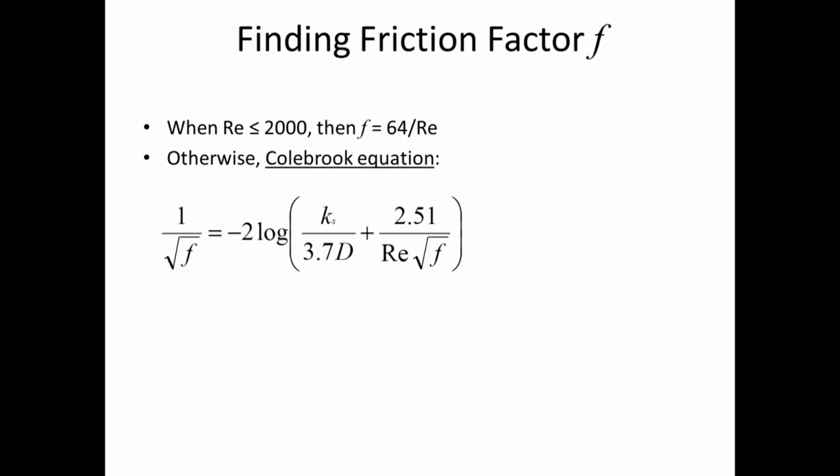Here it is. This is the Colebrook equation. You know, I've been hinting starting in fluid mechanics that there's this really hard way to find the F value. You know, I'd give you the F value in an example and say, really, in a real problem, you're not just given the F value outright. Well, here it is. This is what I was hinting at that whole time. It's the full-fledged way to calculate the roughness F value that we have to insert into the Darcy-Weisbach equation in order to find head loss due to pipe friction.